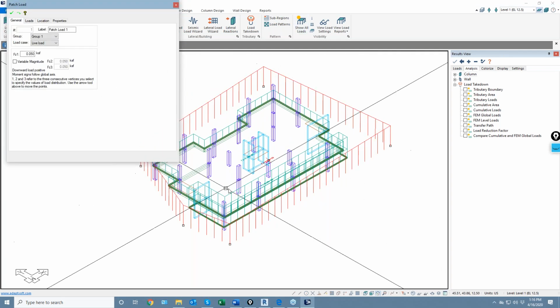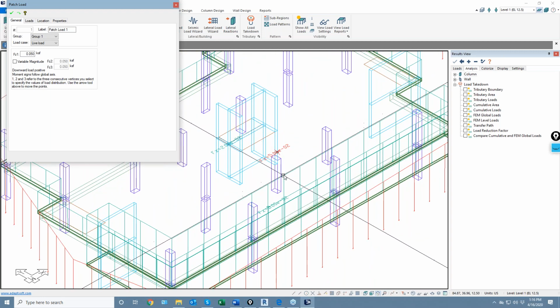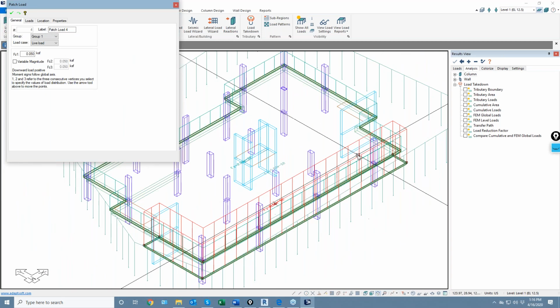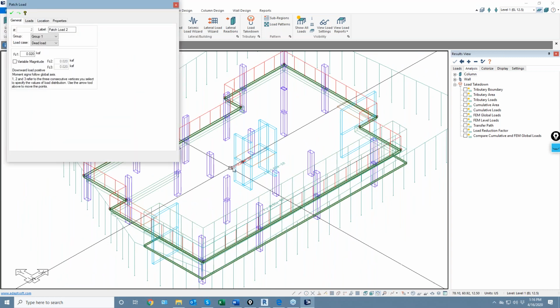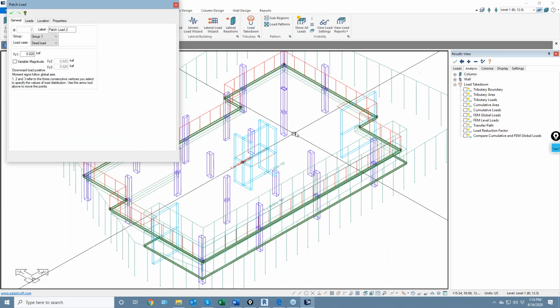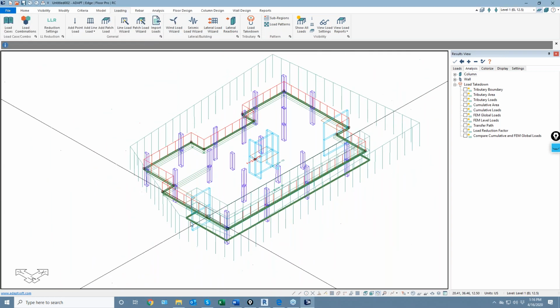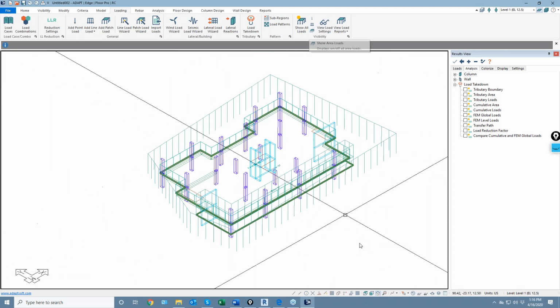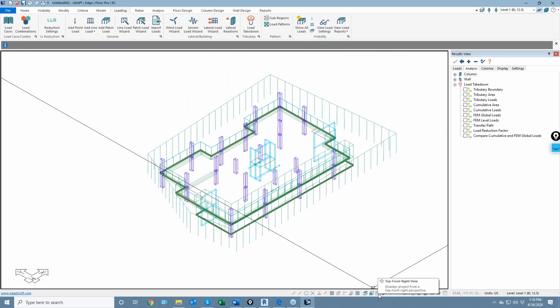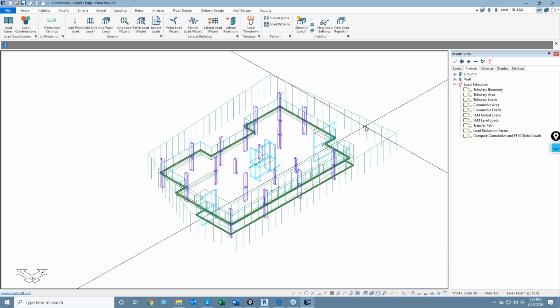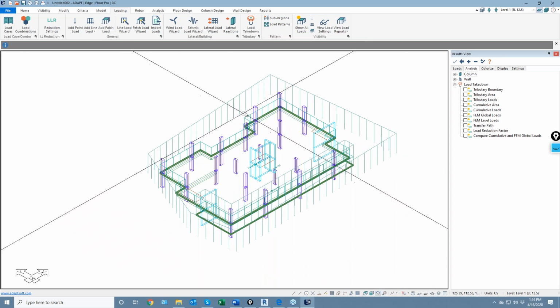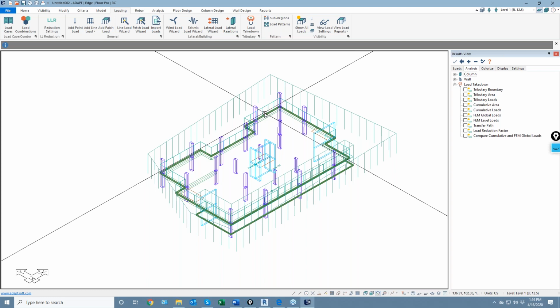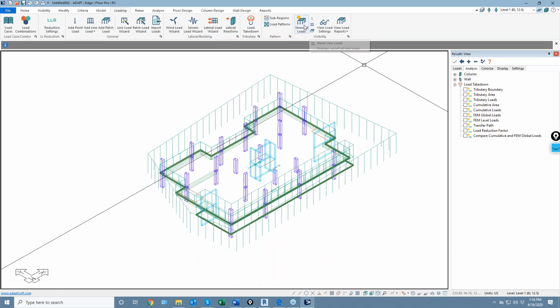So we have our 50 right here. We have our other 50 there. That's 100 cumulative. And then our 20 again mapped to the outer slab region. So that's the loading on the floor. If we wanted to reduce live load for the floor, other than just assigning a set of loads that is already reduced, that's kind of the manual way of doing things, we could do the following, and this shows the example of skip loading.